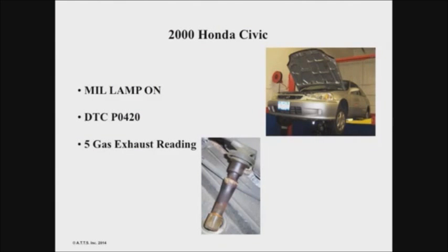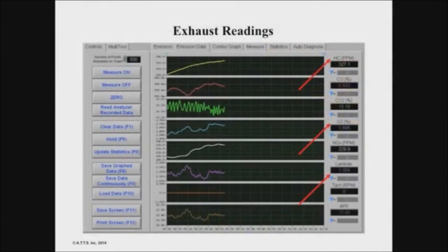When I have an oxygen level, you should know that cars, if you look back in the beginning, the original oxygen reading I told you should be definitely under 0.5%. We're at 1 point something. That means I got a misfire in this motor big time, okay? We see lambda is high, it's way over 1. You got an issue. So we got stuff to back it up.